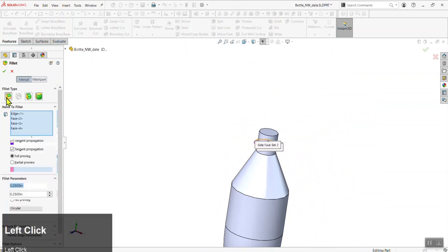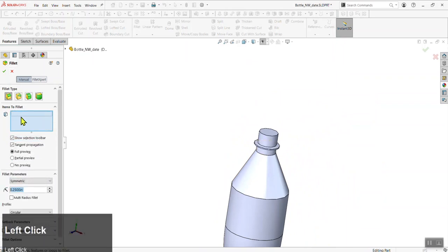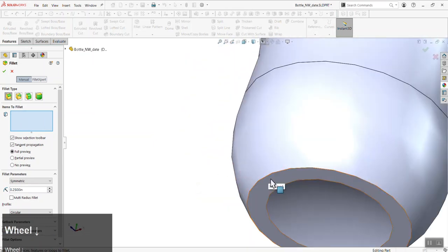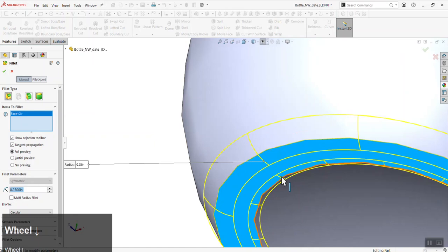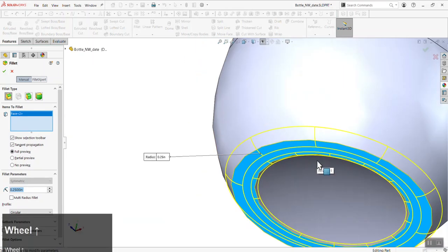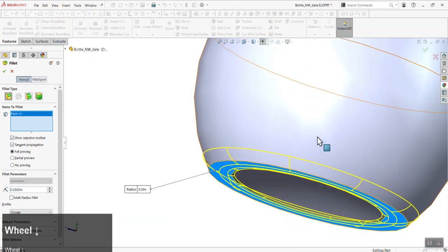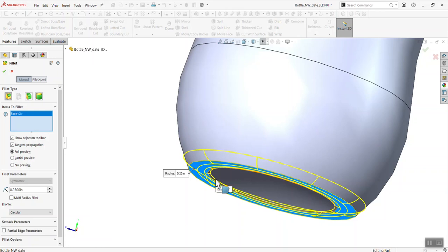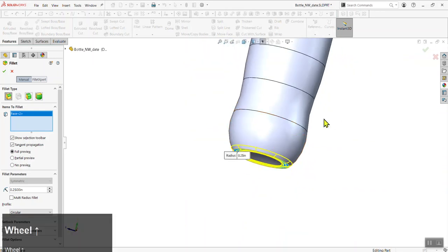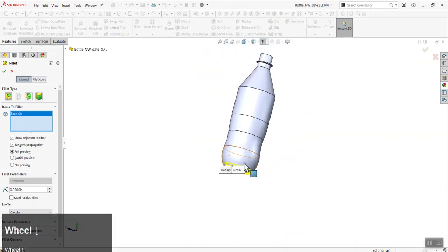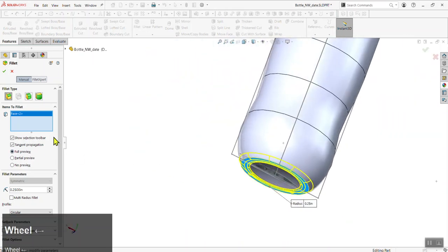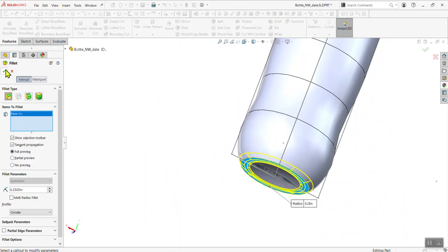In this case, what we want to use is just this first fillet type, and I'm going to clear the selections here. It's worth mentioning that I said you select an edge, but you could select a face, in which case it will apply the fillet to all edges of that face. The first one I'm going to put in here is this bottom footprint, and I measured it to about 1/4 inch. This is basically judged visually. You could also use the image in your sketch to double check. So I'm going to do the base at 1/4 inch, and go ahead when I'm happy with that.